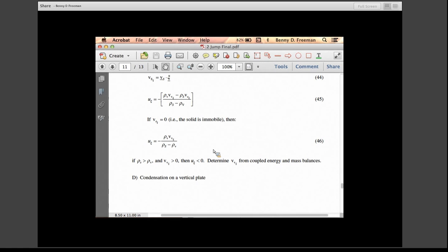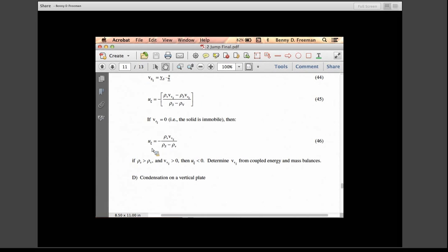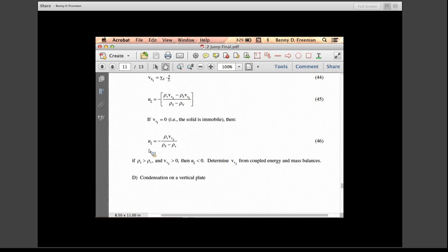It also gives you a rigorous way to relate the interface velocity to the local velocities in the phases around a system. And it shows you, in this particular case, the interface velocity can be orders of magnitude different from the velocity in the vapor phase. And we've said the velocity in the solid phase is 0. So those three velocities, the velocity in the solid phase, the velocity in the vapor, and the velocity of the interface, are separate and are not at all equal to one another, right? And so this gives you a way to account for complex moving boundary conditions, essentially.